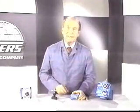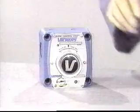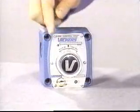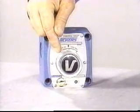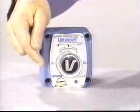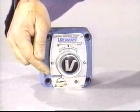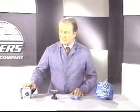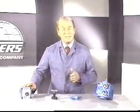It's installed in the circuit by means of threaded pipe ports. Now, this is the unit that's both pressure and temperature compensated. The knob on the front allows us to set the throttle opening, and the key is a means of locking the setting. The valve is installed into the system by means of a subplate, which has matching in and out porting.